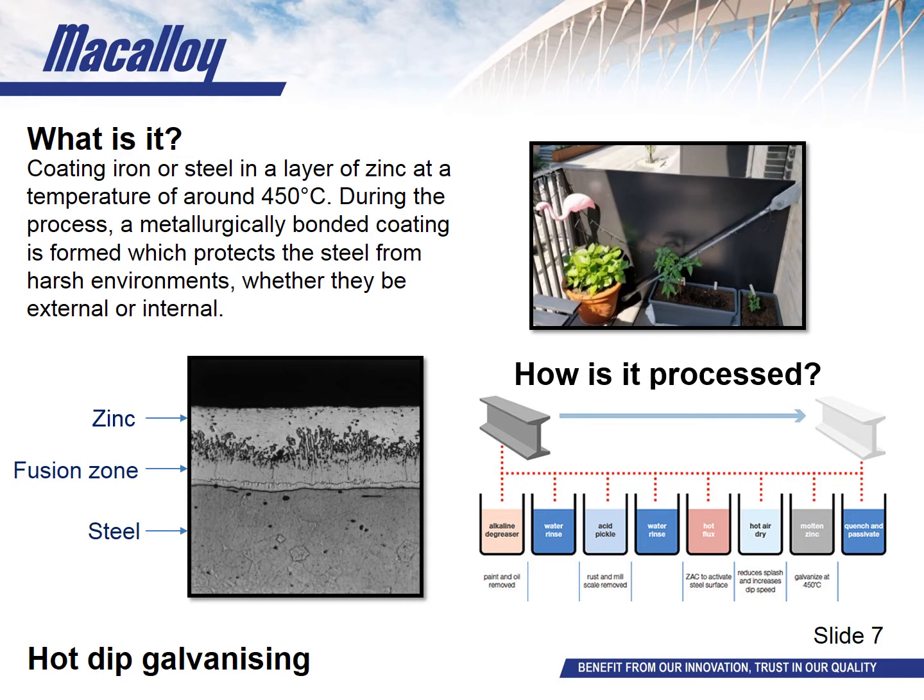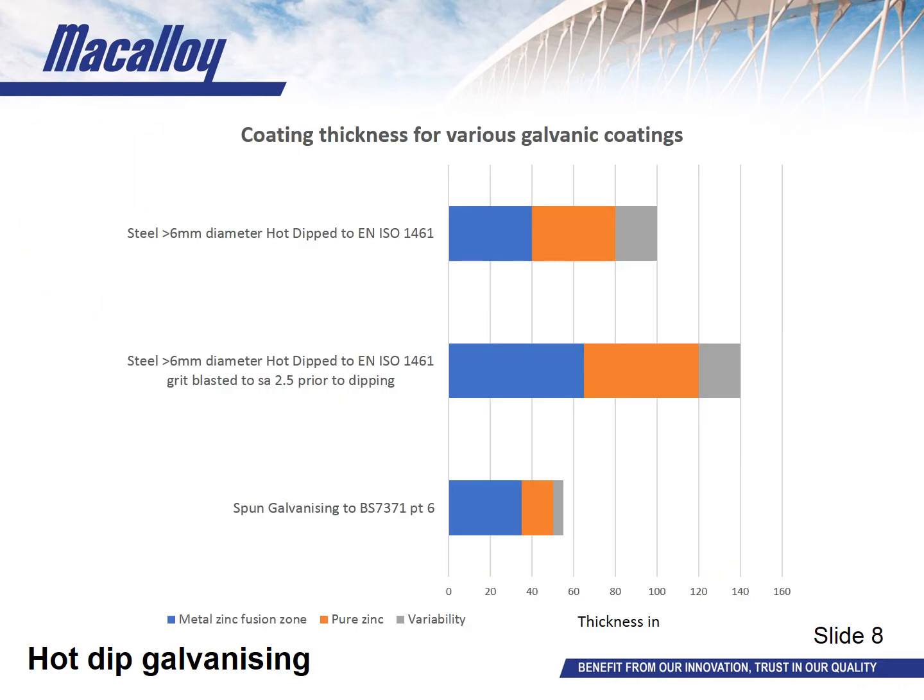Conditions in the galvanizing plant, such as temperature, humidity, and air quality, do not affect the quality of the galvanized coating. With galvanizing, thickness matters. This slide shows the thickness of zinc provided by the various galvanizing processes. The zinc pickup and colour of a galvanised surface can vary with the steel grade. High silicon steel has a higher zinc coating.